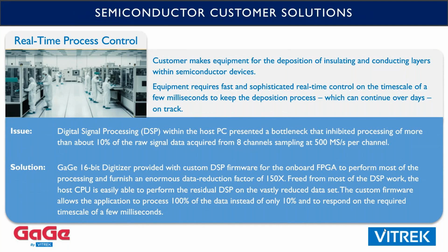So the FPGA is a big chip that is more like configurable circuitry, software configurable circuitry. So instead of data moving around as controlled by a CPU, it's more flowing through circuitry in a pipeline fashion, which can move data hundreds and thousands of times faster. Now, this FPGA is less than half full with standard GaGe functions. And up until maybe 15 years ago, we just concentrated on getting the raw data to the user as quickly and as easy to use a fashion as possible.